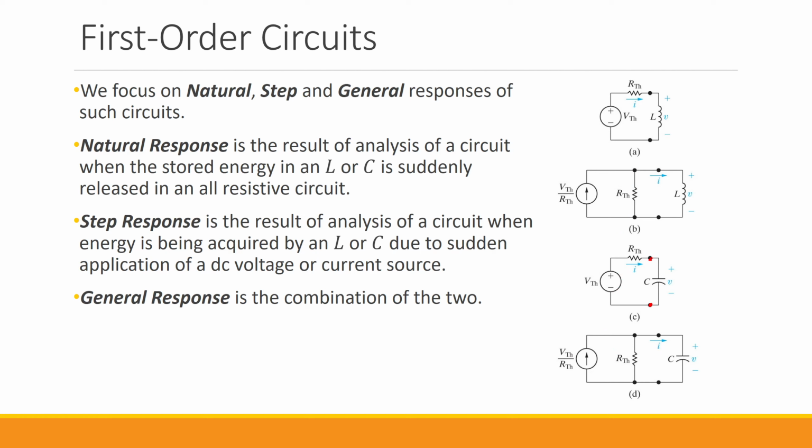We can also consider that these are equivalent inductance or equivalent capacitance, right? So we consider them capacitors or inductors. We calculate the Thevenin or Norton equivalent circuit connected between their two terminals, and also, if needed, we calculate their equivalent inductance and capacitance too.